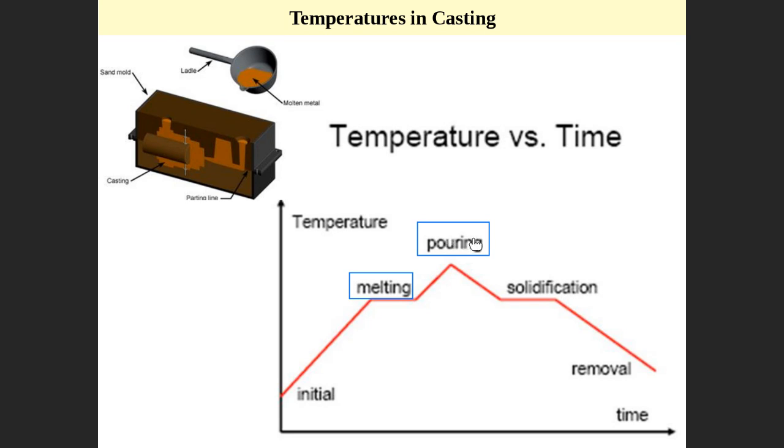So we heat the material up to the melting temperature, and then heat again up to the boiling temperature. So what is the boiling temperature? It is around 100 to 150 degrees Celsius above the melting temperature. Why do we do this? Why don't we just melt the material into a liquid and do the casting? Why do we have to heat the material more than the melting temperature, adding some heat after the material becomes liquid? Because when you pour the material in a mold, the mold is cold.